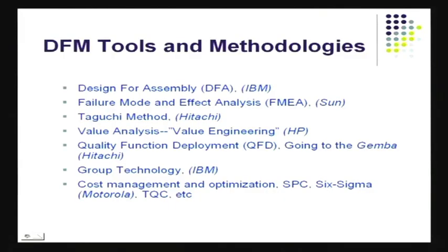You also have the Taguchi method. That's also another design for manufacturing tool, and we discussed Taguchi methods early on in this course. That's one method by which you can create robust designs. Your design should be such that the final performance is on target and it's not affected too much by the environment. That is something that Dr. Taguchi came up with.